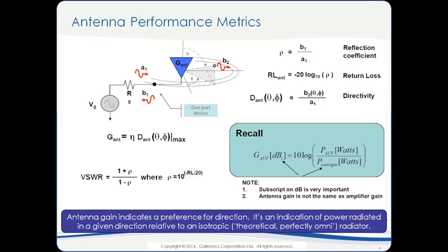And obviously the ratio of the radiated power to the accepted power is an antenna efficiency. That's a very important quantity. Unfortunately, we don't see that on data sheets for macro or even DAS and small cell antennas. But what it tells us is how lossy the antenna is. Typically in directive antennas, like the outdoor macro antennas, the loss in the system is not as critical as directivity is, or what is the beam width of the antenna in the elevation and the azimuth plane.